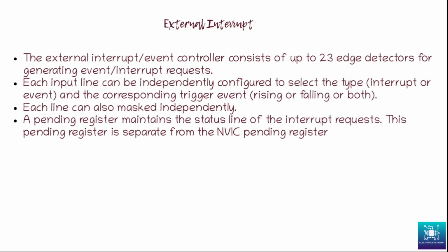These are generally interrupts that are coming from lines outside of the controller. Though we can also generate an external interrupt from software, which is called an event request, generally these will be interrupts that are coming into the ports of the controller.